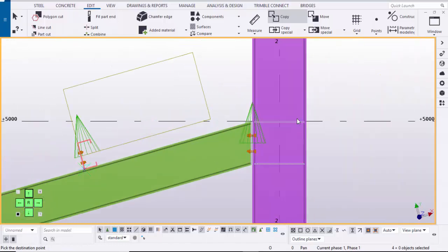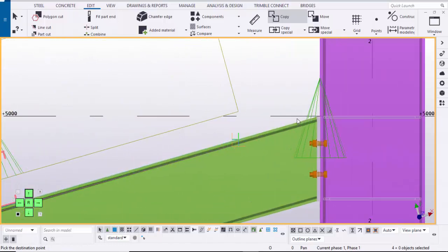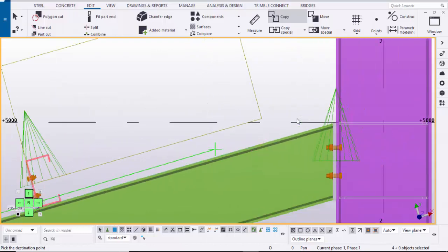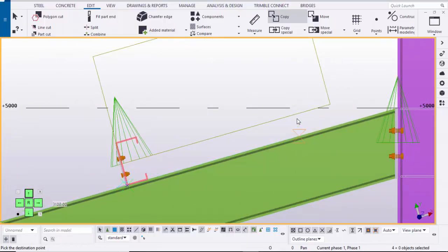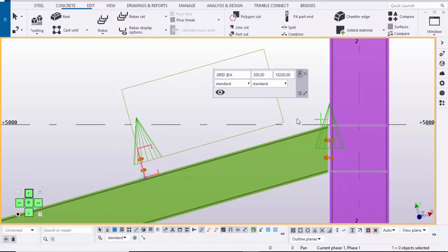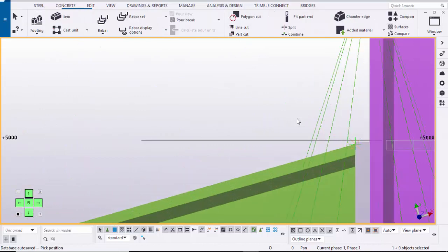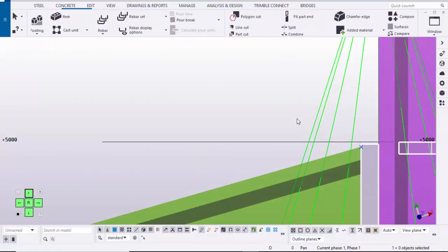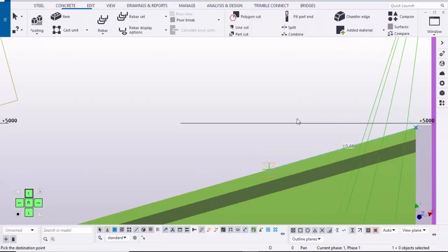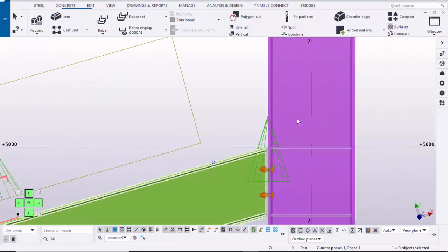Press here, and you need to place one more point here, but there is no point. So we're going to create one more point at this location. So click on escape and take the reference point here, select it, right click on mouse, move from, pick the first point and place the cursor on the edge of this rafter. Don't click on it, just place the cursor and enter the value. Let's take 250 millimeter, then click on enter. Now we have the point here.